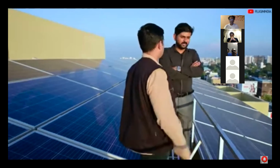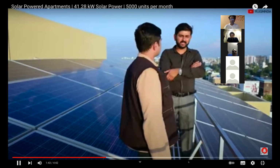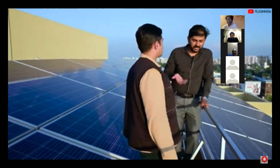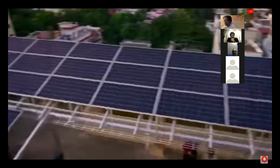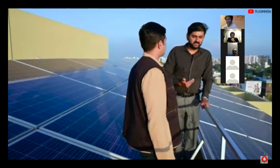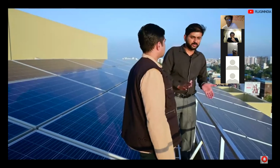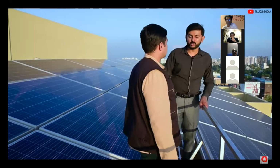So the 41.28 kilowatt solar system is connected to a net meter. The reason we have done that is so that we can export the excess electricity that's being generated that's not being used. So what happens is that when in the night there's no sun power, the excess electricity that you have exported, you can essentially take it back. So MSEB, the electricity board, acts as a virtual battery. Right. So in this situation, continuously, even though there's no sunlight in the night, they're still getting solar power through net metering.